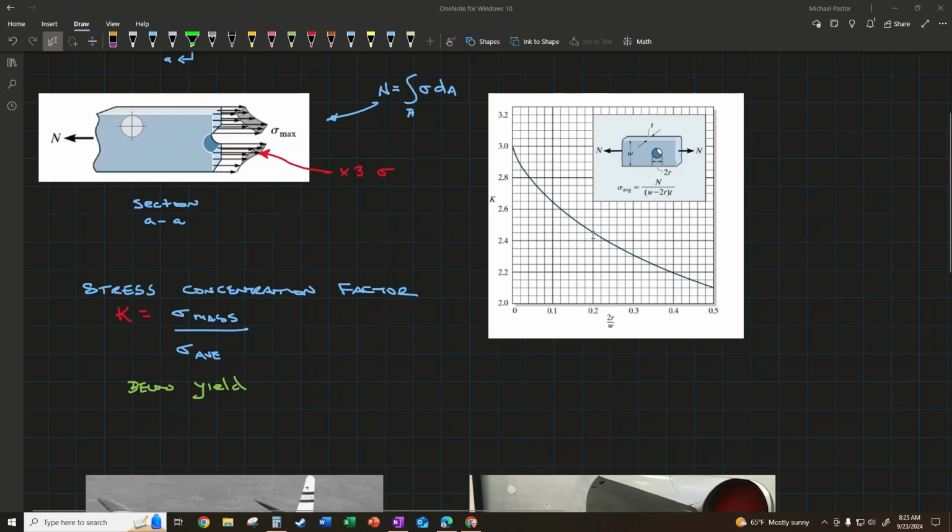Well, I would just cross-reference that on this line, and it looks like I would have a 2.45 stress concentration right here. So 2.45. And you would just multiply your stresses by that value to calculate essentially any situations or effects. If you were designing, that would be your design stress that you would have to correspond to or defer to.